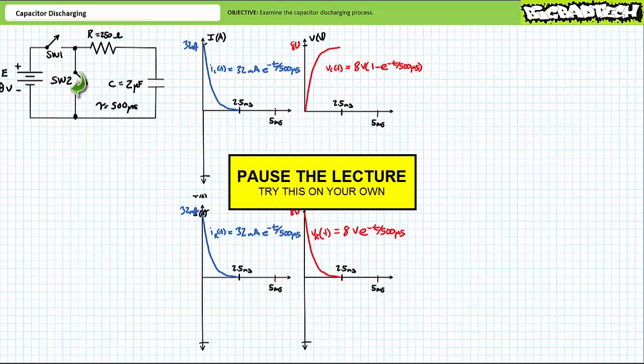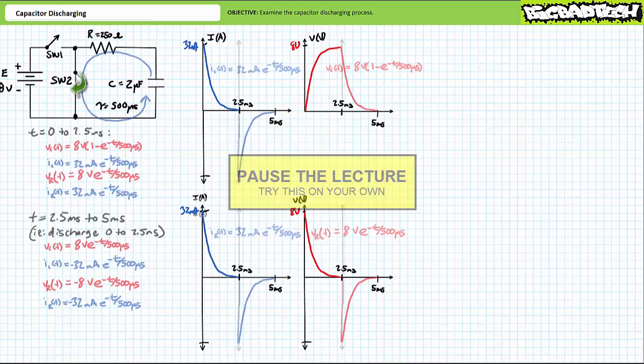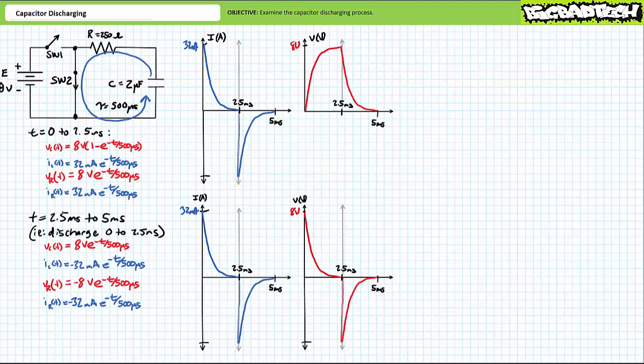If you're tracking, you should have arrived at the following conclusion. During the discharge process, current flows out of the capacitor and through our only resistor right to left. Current flow in the whole system is in reverse direction. The initial surge of outgoing discharge current must therefore be negative for both the resistor and the capacitor. As an additional consequence of this reversal of current, voltage across the resistor now appears positive to negative, right to left. We also might expect voltage to be negative for the resistor.